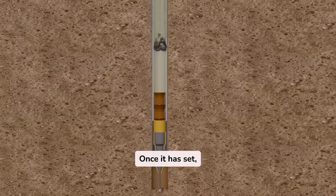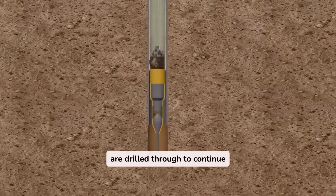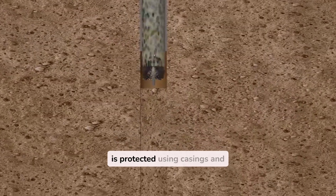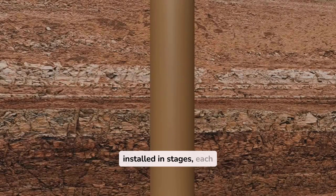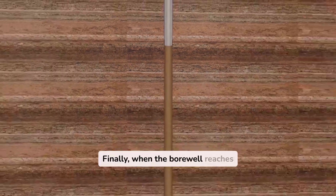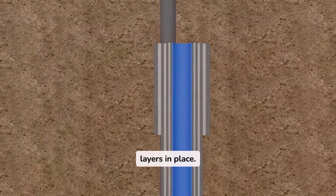Once it is set, drilling resumes, and the bottom and top plugs are drilled through to continue further. In this way, the well bore of an oil rig is protected using casings and cement layers. As the depth of the well bore increases, new casings are installed in stages, each secured with cement, providing ongoing stability and safety. Finally, when the bore well reaches the oil reserves, there are multiple protective layers in place.